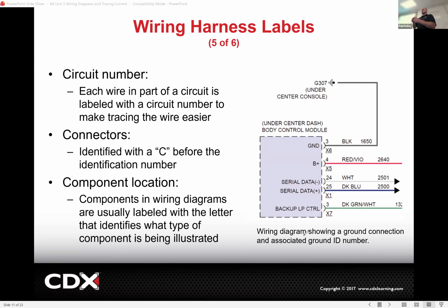repin that connector. So you could carefully remove the terminals, cut that off, crimp a new terminal on, and reinsert in the correct location. That doesn't sound hard, but when there's that many wires, I'm gonna tell you, it was a little bit rough. So knowing where all these terminals are is necessary when you got to test it, but also just in the case that you need to do a repair, like I find out pretty early, like, hey, I've got to repair all these terminals. And I spent like a couple of days, whole days, not like class periods, like whole work days. Terminal, crimp, cut, terminal, crimp, cut, unpin it, repin it, unpin it.